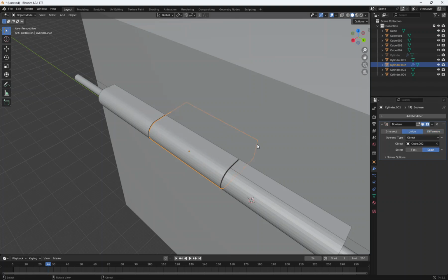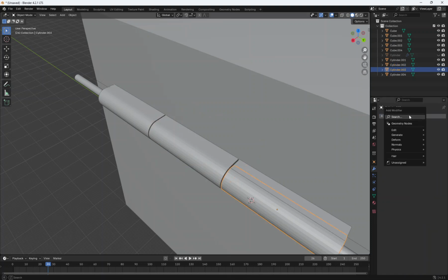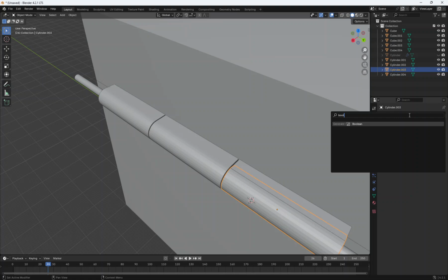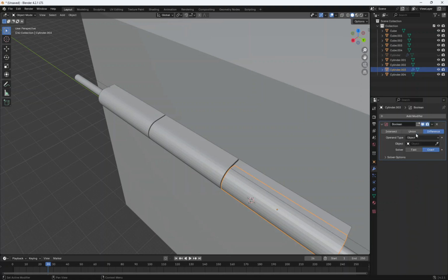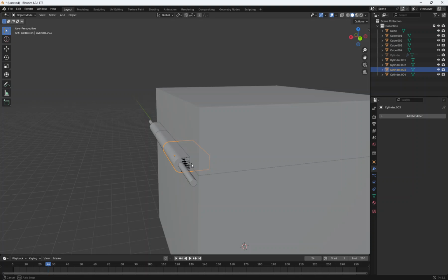You can see here that it extends that geometry highlight. And then hit apply. And then same thing with this one. Boolean. Join. And then we want to pick the other box and apply. Okay, so now we've got these two.